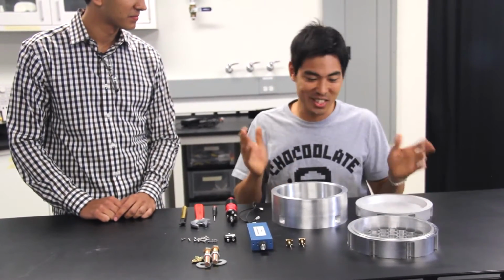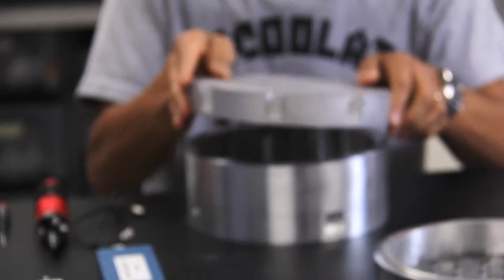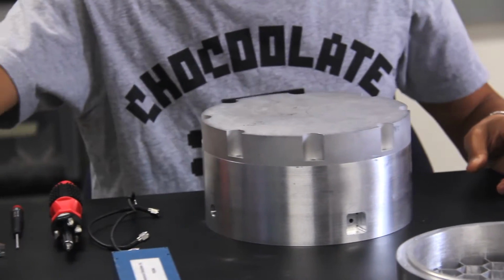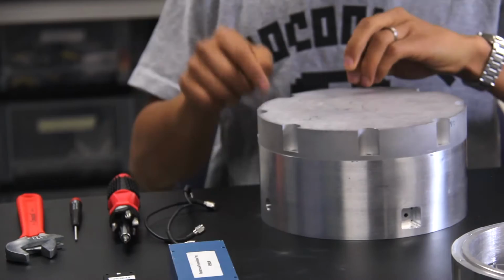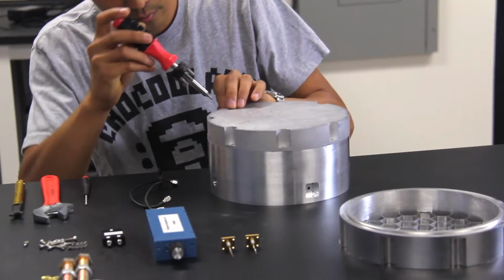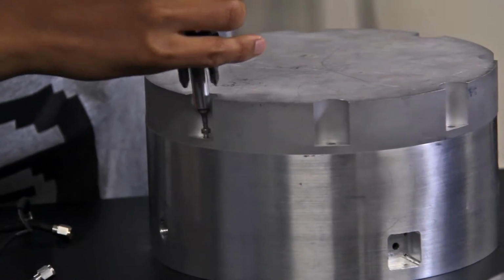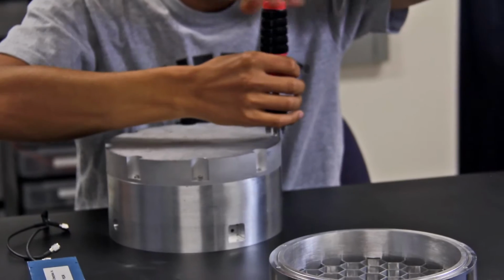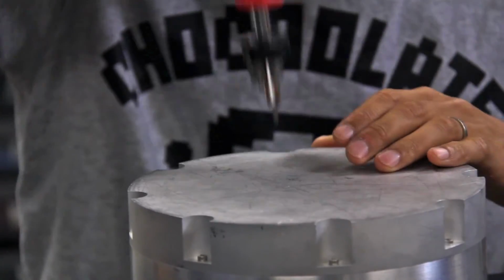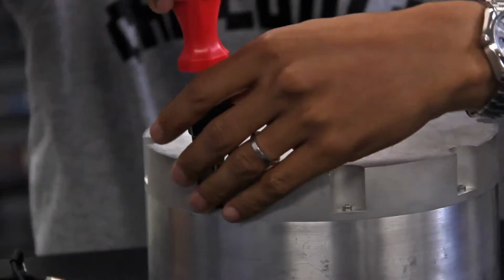Okay. So let's get started making the bottom parts. To make the cavity, the contact between the different layers is very important because there's a current leakage which makes the cavity's efficiency drop. So make sure you tighten the screws. To tighten up each of the layers, you have to screw in a cross formation, something like this.